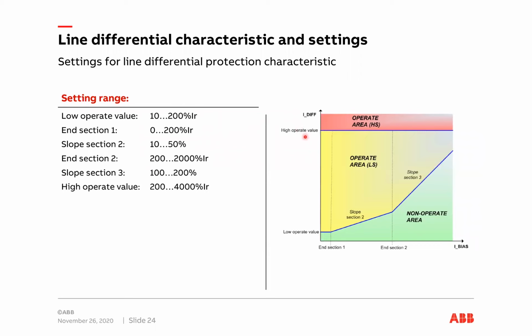We also have a high operate value available here. The high operate value will clear the fault without any operation delay, and it will not consider any inrush blocking.